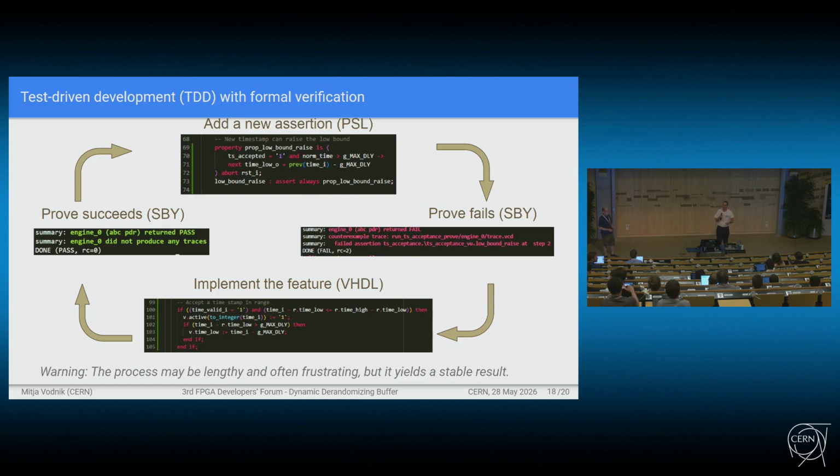It would be fun to compare one developer doing it with simulation and one with formal verification, and see what would happen. But it's definitely more straightforward to do test-driven development because each assertion literally corresponds to one feature. So it's very easy to do this flow. Whereas in a simulation, I don't see it as so straightforward. Like a UVC basically covers the whole data stream. You can't really go step by step. If that makes sense, yeah.